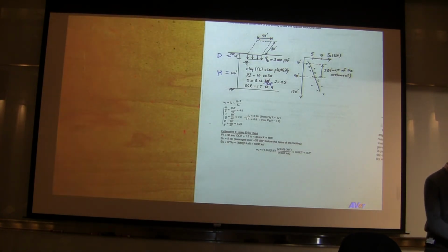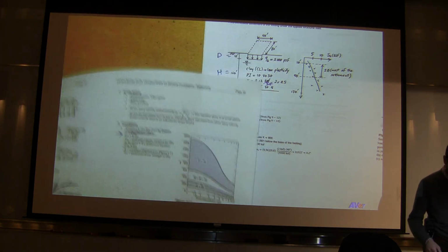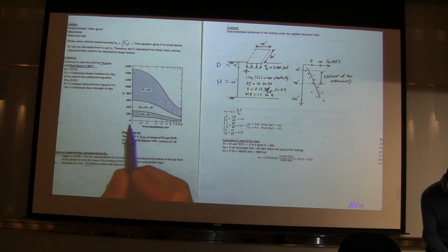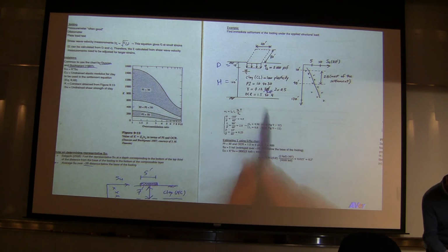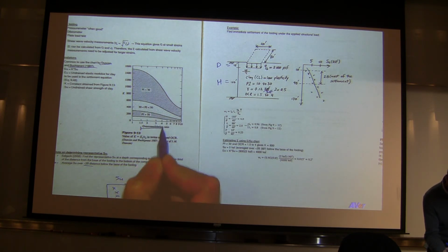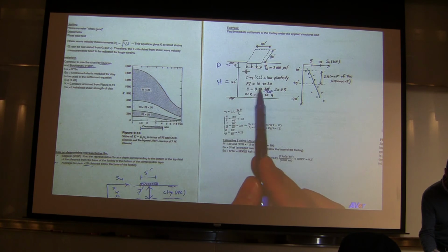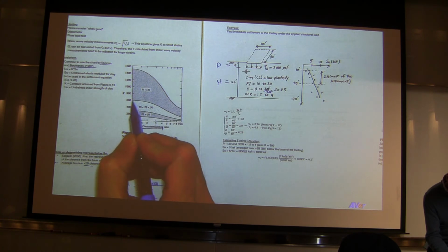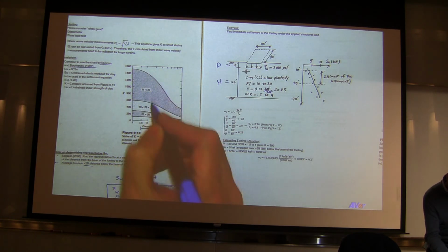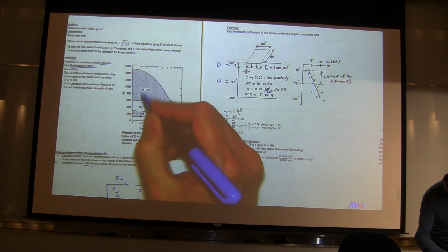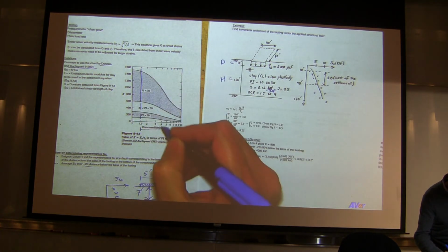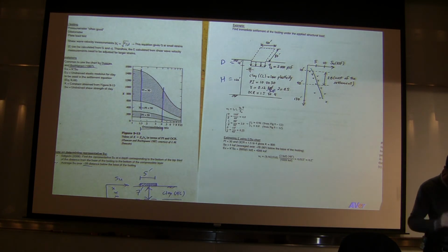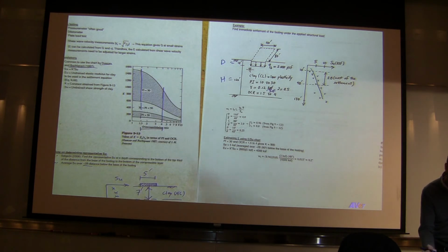So let's look at the graph, the Duncan equation here. So OCR is between 1.5 to 4, so we are from here to here. And PI is 10 to 30. So this is almost a 30 range. So we are somewhere here. So we have values that are between here to here. What would you pick in this range?